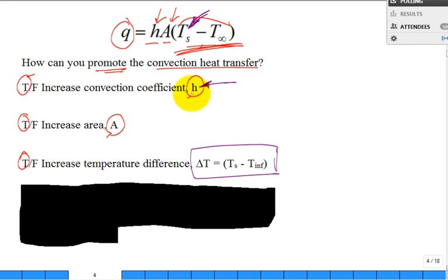But when you run up to a red light and stop, you need the fan, and you need a piece of plastic that goes around that fan and seals it with the radiator. It's called a fan shroud. I did this when I was about 17. Rebuilt an engine, took the fan shroud, just a piece of plastic, threw it out, don't need it.